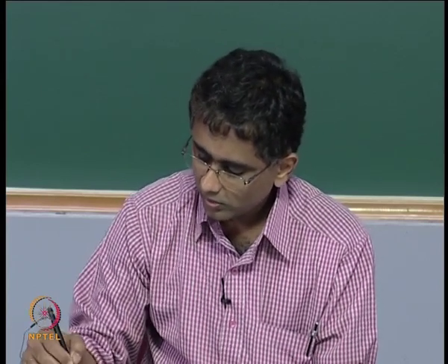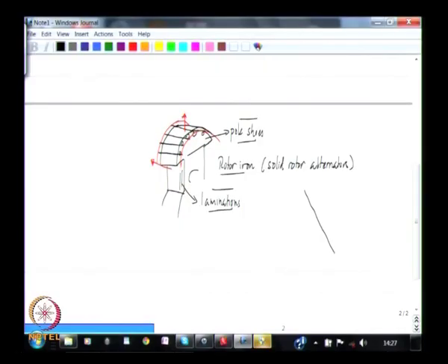We may go for an arrangement where if you have the dq axis of the rotor, this is your d and q fixed to the rotor, in order to represent the fields produced due to a disturbance in the rotor speed or in the air gap field, you may have a coil represented on the d axis and a coil represented on the q axis. This is the barest minimum.